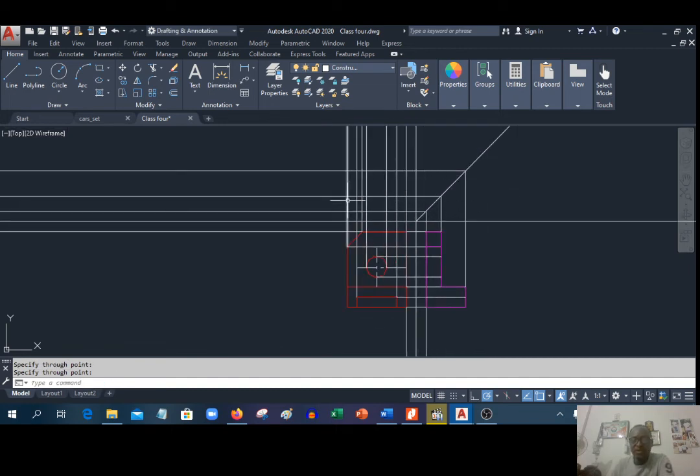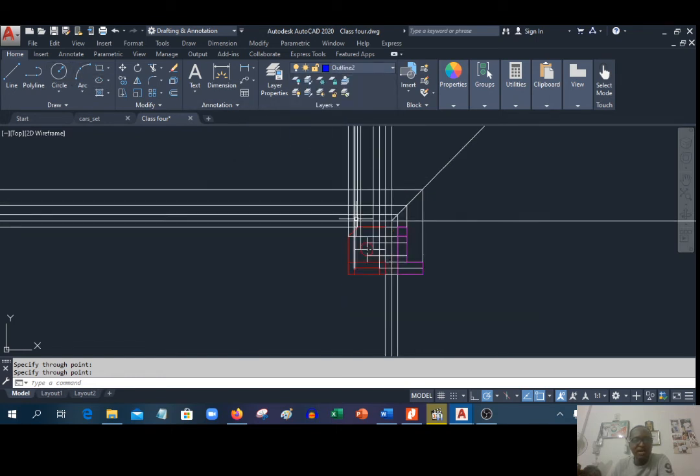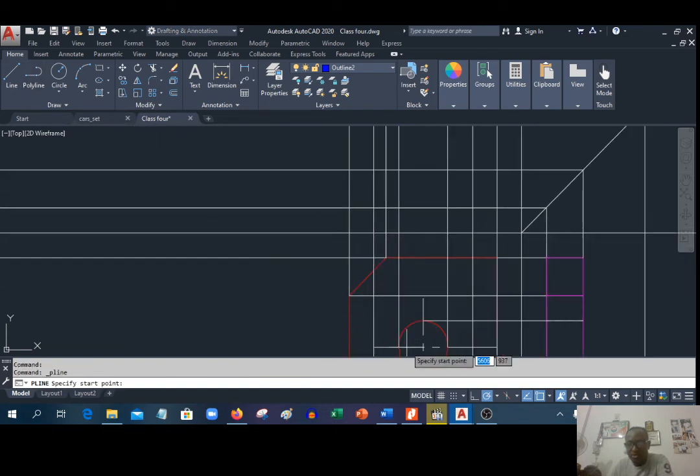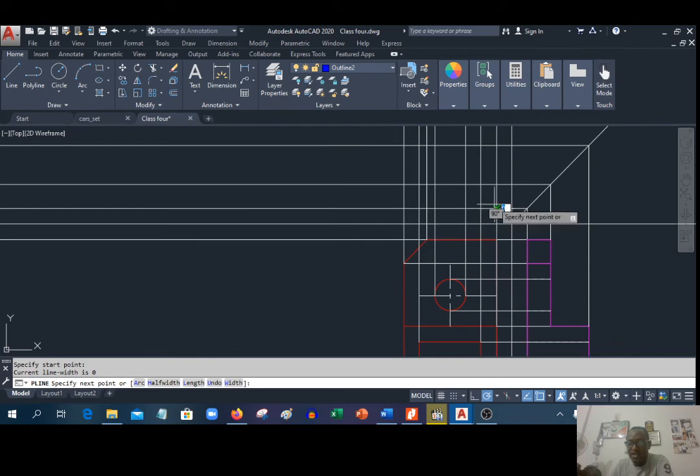Let's try and break out this drawing now. So I'll change to the 2, this time from the plan. Let's click on Polyline. You need to be careful here. You trace the drawing, which starts past this projection line. So your drawing starts from here, goes all the way to the top and all the way down. You draw the first visible box first, then we'll close.